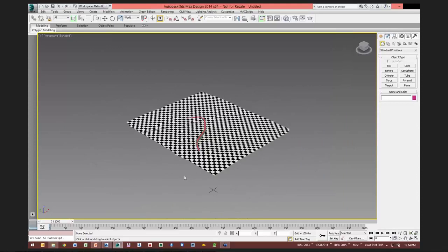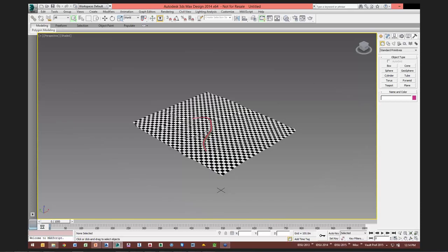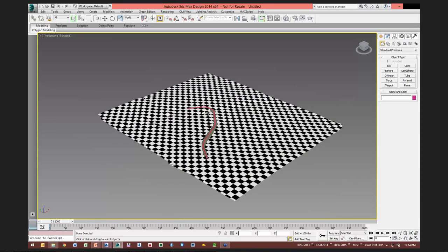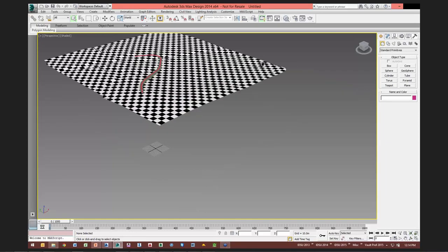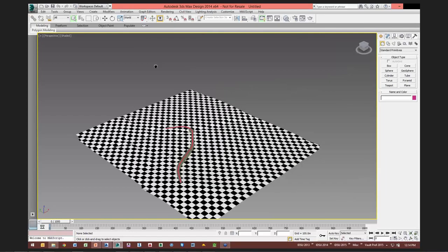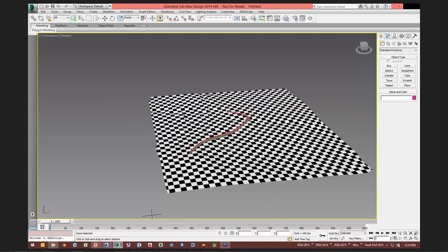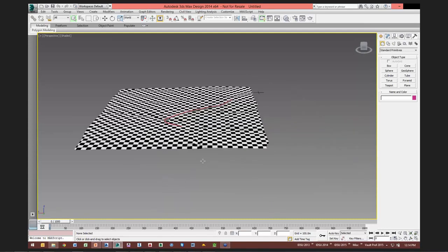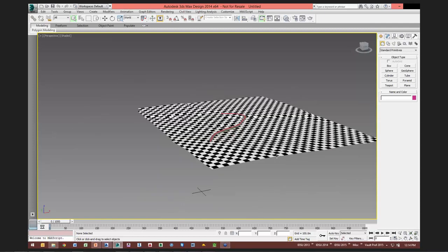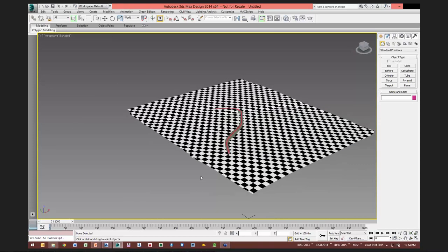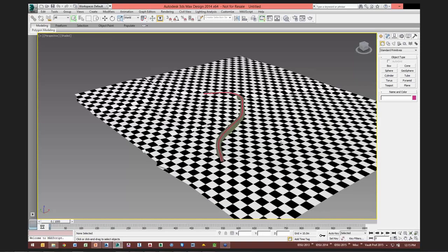Okay. So a couple things about navigation in 3ds Max. It's pretty similar to AutoCAD products. I use the mouse wheel to zoom in and out. I use it to pan. Now the panning I get is more of a perspective type view. Then the one distinction is I hold the Alt button with my mouse wheel to do orbiting. In AutoCAD, not generally a good practice with 3D objects, you would be holding Shift and your mouse wheel, and here it's Alt and your mouse wheel. So just a little something to keep you on your toes.